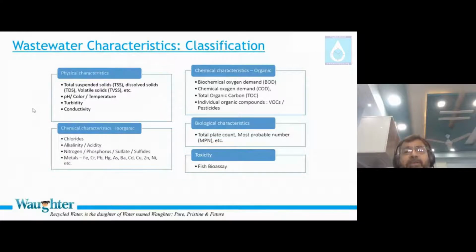Another measurement is to just measure total organic carbon using an instrument. So how do you measure organic carbon? You burn all the carbon, it becomes CO2. Dissolve the CO2 into water, it becomes H2CO3. H2CO3 is a weak acid. Titrate it with alkali, you get the number. So the TOC is a value of your organic impurities.